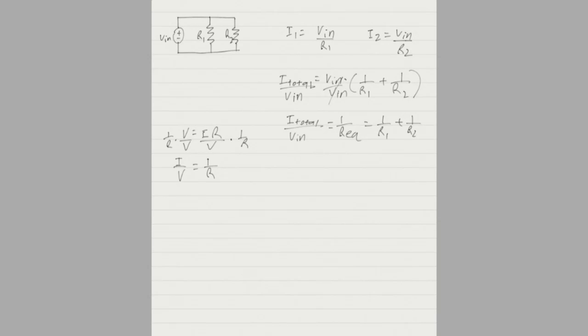So this is how parallel resistors work. If I were to extend this chain up into infinity, then I could extend this into infinity as well, so I would do plus 1 over R3 plus and so on, up to 1 over Rn. What you need to know for any of these problems is just how to do two elements in parallel, because you can simplify things down in a chain. If you had 3 resistors, you could combine two of them using what I'm about to show you to get 2 resistors, and then combine those 2 resistors in parallel into 1 resistor.